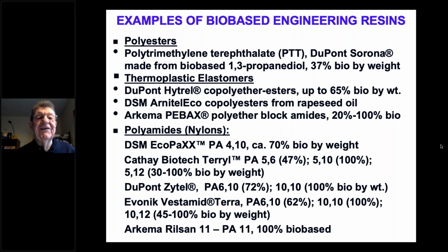Let's switch gears a bit. I'll talk a little bit about bio-based engineering resins, commercially available ones, polytrimethylene terephthalate, the DuPont Sorona material. Large applications here are carpet fibers, of course, but also being used for bio-based engineering resins using bio-based 1,3-propanediol as a monomer.